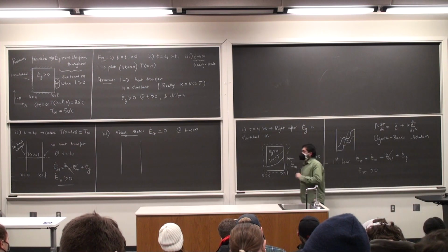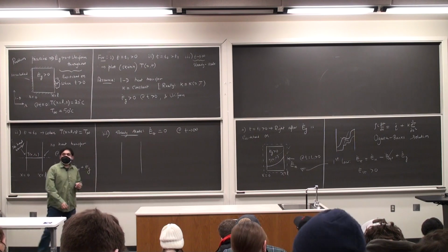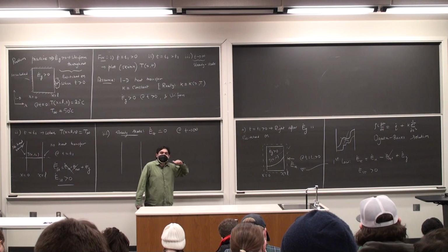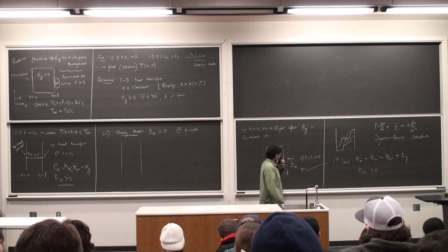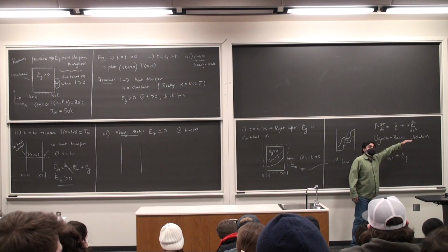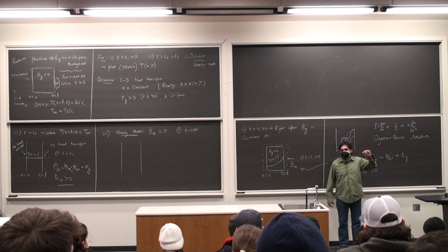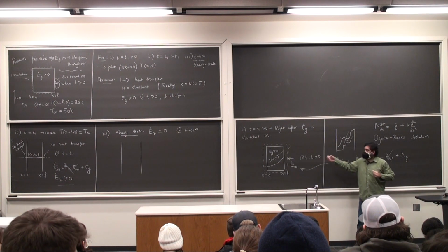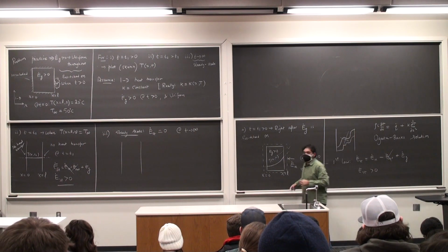And for the kind of assumptions that we have in our problem, where the thermal conductivity is a constant and you have volumetric heat generation that is uniform, for a given time, you will find out, if you look at the solution, and I'll post the solution, we won't be looking at it of course. At a given time, the temperature profile will be a combination of an error function and an exponential curve. So it will look like the sort that we have drawn here. It will not look like this guy. Once again, this is beyond what we are doing.